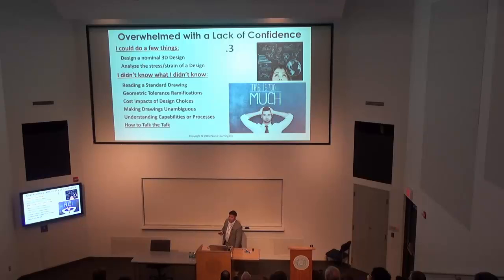Are they going to come back with 0.3? This is tenths, right? This is in math. You have the tenths, the hundredths, and thousandths. You've learned that, right? Well, this would be 300 thousandths. And 3/10 to a machinist is actually this. It's 1,000 times different. It's just a terminology difference. But we never talk about it. We never talk about these differences in the way that we teach things and the way that it actually goes on the shop floor.